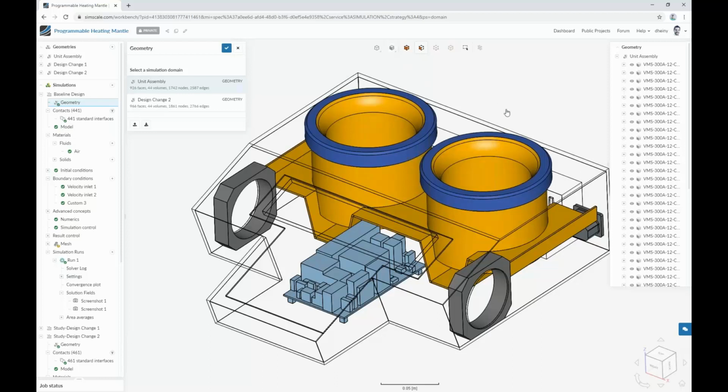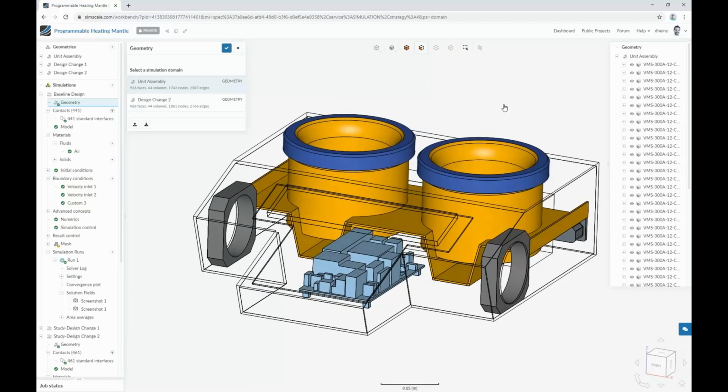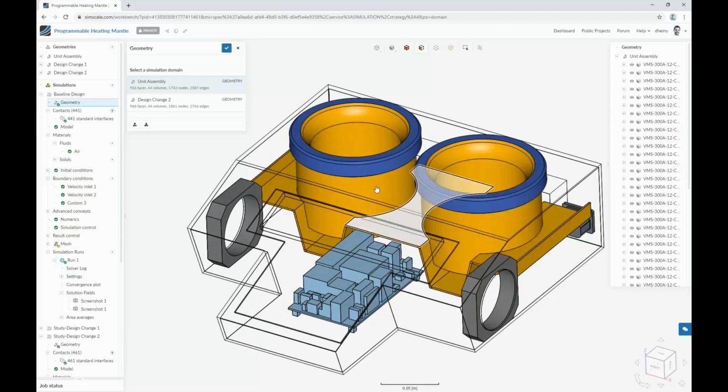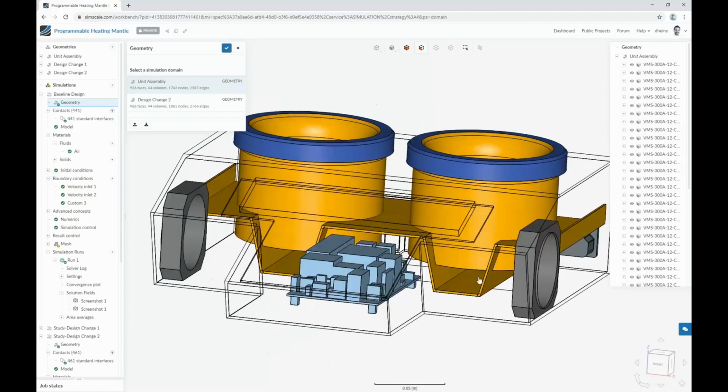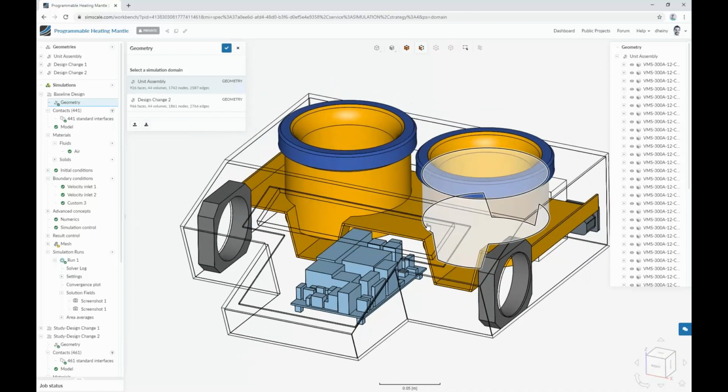In this case, we're looking at a thermal analysis of this model, and we want to look at not just conductive heat transfer, meaning how the parts emit their heat and how it travels through other parts. Because convective cooling is important in that model, we do need to model the airflow in here as well, right? Hence, we're going to run a conjugate heat transfer analysis in which we look at convection and conduction. In this case, we turned off radiation. We could also model it with radiation, but we disregarded that.